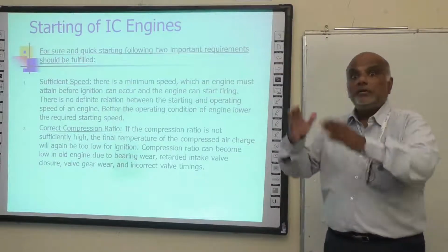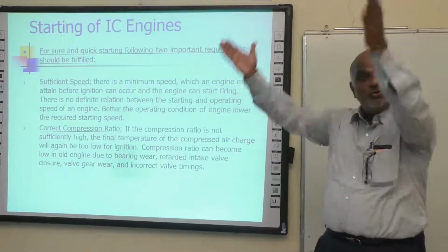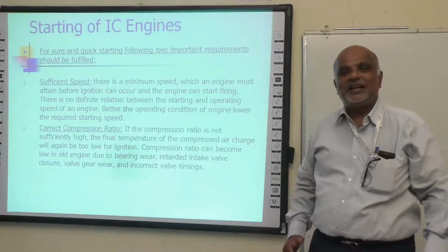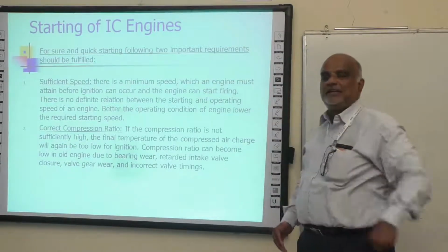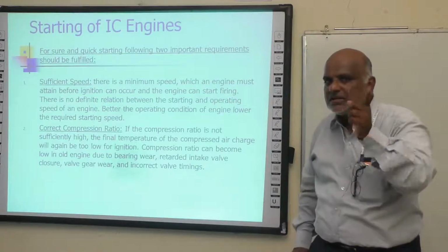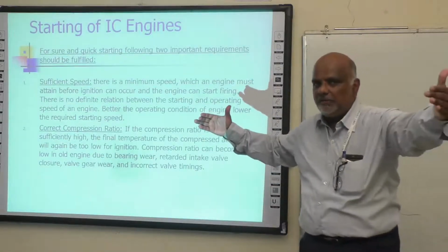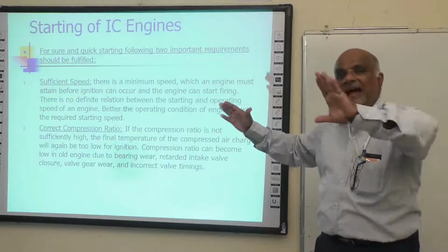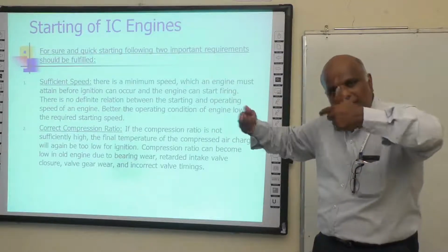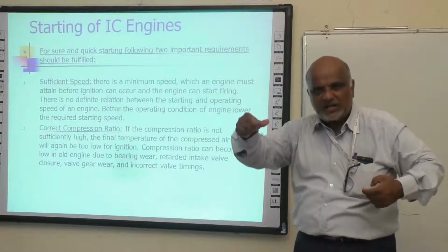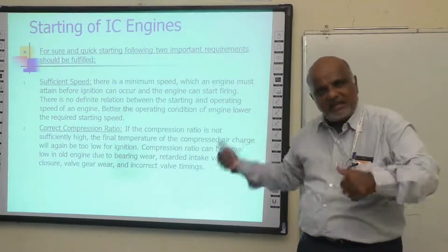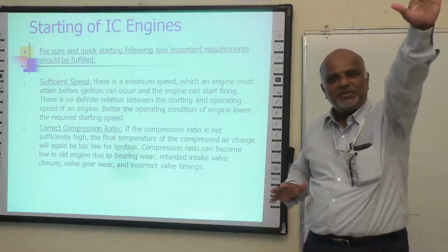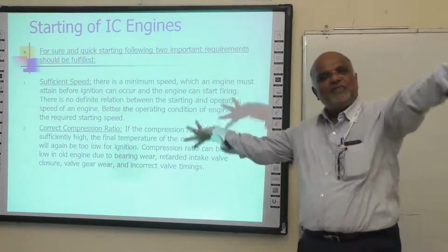No. For starting of the engine, when you have two main air bottles, you fill up the main air bottles to a pressure of 30 kg per centimeter square and use that air for starting of the engine. Now watch this. You are not using this air during the entire voyage for starting. You are only initially using this air for starting of the engine, and then after the engine has picked up momentum, as you take your hand off the starting air button on your bike, the same way here, the air is cut off and kept as reserve. The engine now runs on fuel.